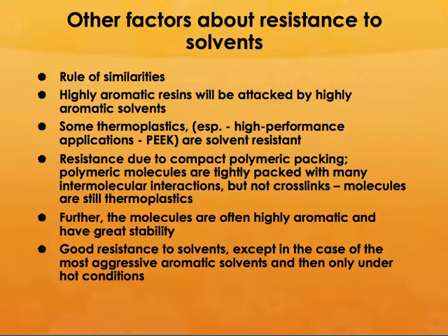But you will see that some of the thermoplastics, especially for high performance applications like polyaryl ether ketone, or they call it PEEK, are extremely solvent resistant. But there are some types of polymer matrices that do not have very good resistance to solvents. Mainly the resistance of these composites is due to the compact polymeric packing.